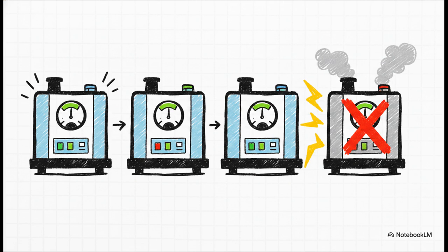Basically, we install enough capacity so that under normal operations, we're using N-1 generators, running at a super efficient 70 to 85% load factor. That way, if one unit suddenly trips offline, the remaining running units can absorb that massive peak load spike without exceeding a 125% overload limit. It keeps the platform up and running without missing a beat.